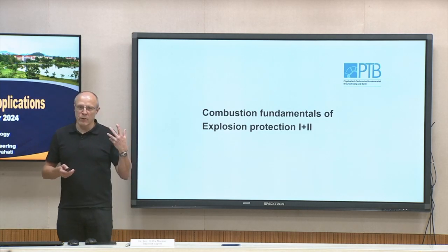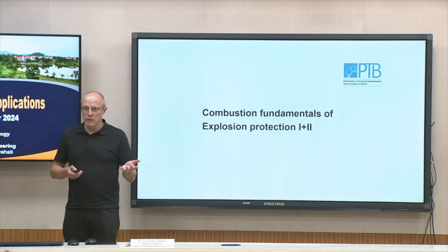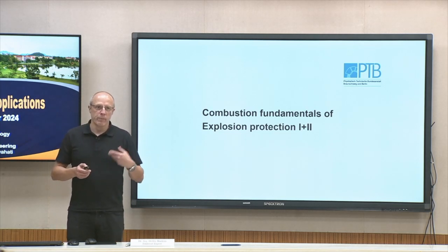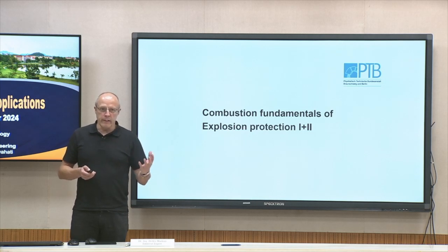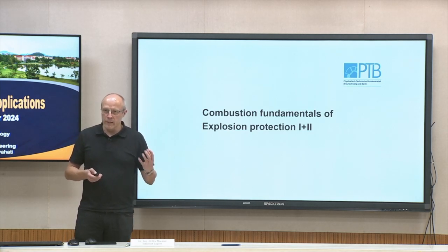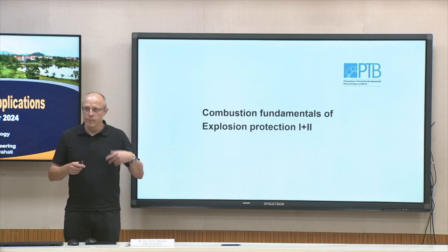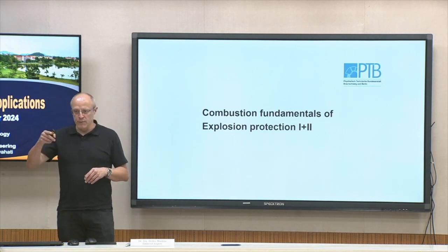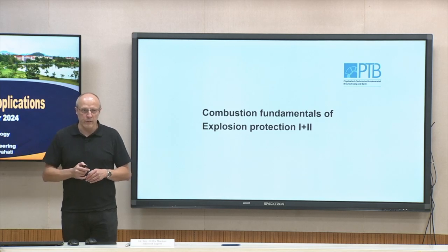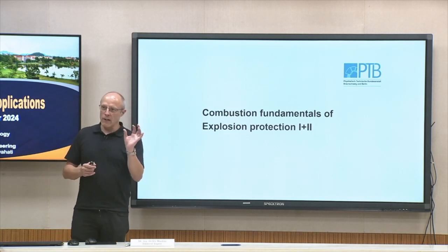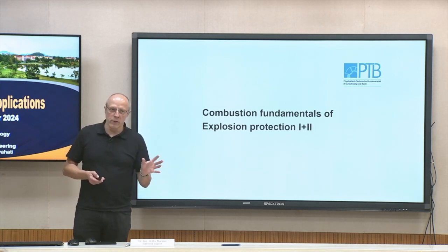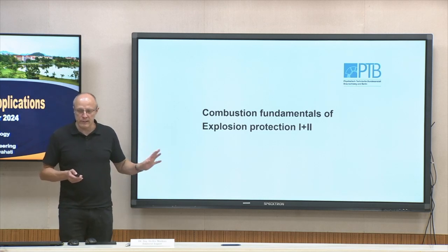So we always have only an energy value, but of course we have to consider the plasma formation, the initial heating of the gas volume, the onset of the chemical reaction, and finally the step to the self-sustaining flame propagation after ignition. So behind this number of 70 microjoule, there is a lot of chemistry and physics which we have to consider. This I will discuss later on.